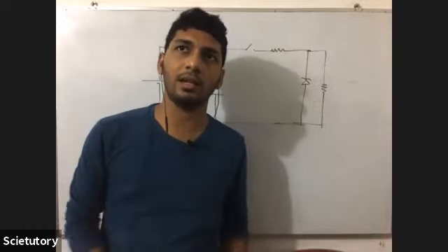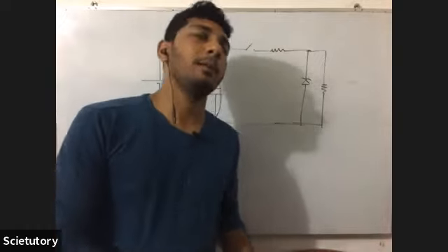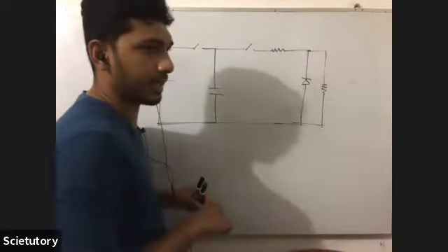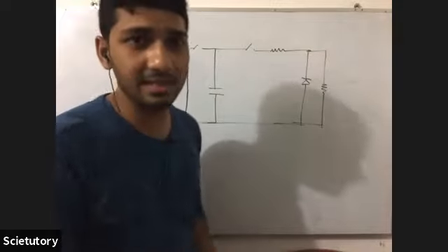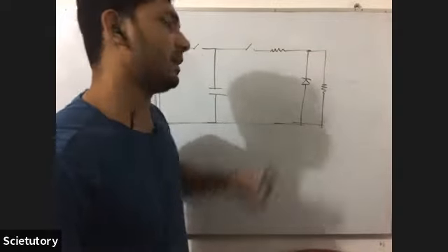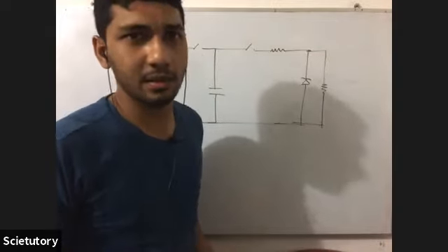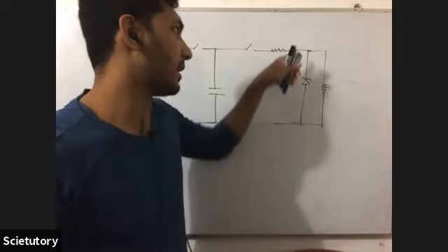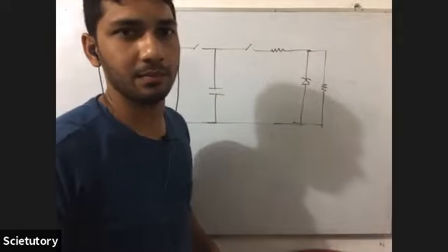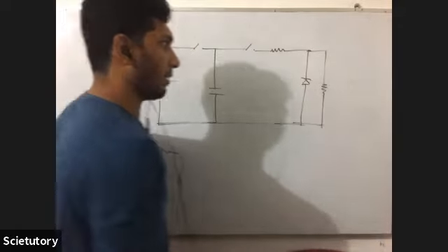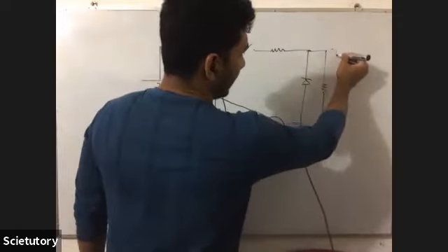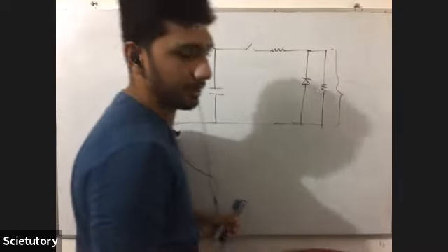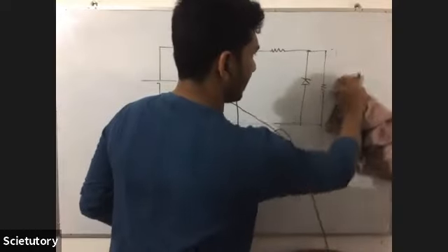When the voltage difference across a Zener diode exceeds its breakdown voltage, the Zener diode breaks down. After that, it maintains a constant voltage difference across its terminals, and also across whatever is connected in parallel to that Zener diode.